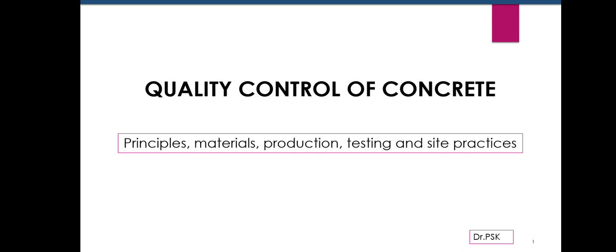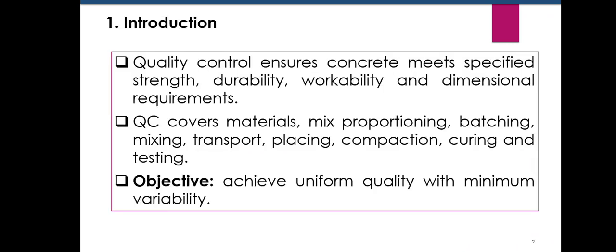Hello everyone. In this presentation, we are going to discuss an important topic in concrete technology, quality control of concrete. Quality control is essential because concrete is not simply a material that is mixed and placed. Its final performance depends on controlling the complete process starting from the selection of materials and continuing through mix design, batching, mixing, transportation, placing, compaction, curing, and testing.